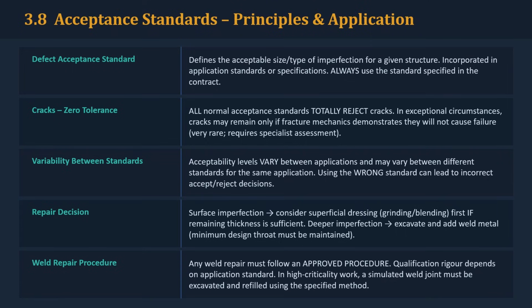This slide brings the acceptance principles together. First, cracks are normally rejected under standard weld acceptance requirements. The presentation also notes that exceptional cases may require specialist fracture mechanics assessment. That is not a routine welding inspector acceptance decision.